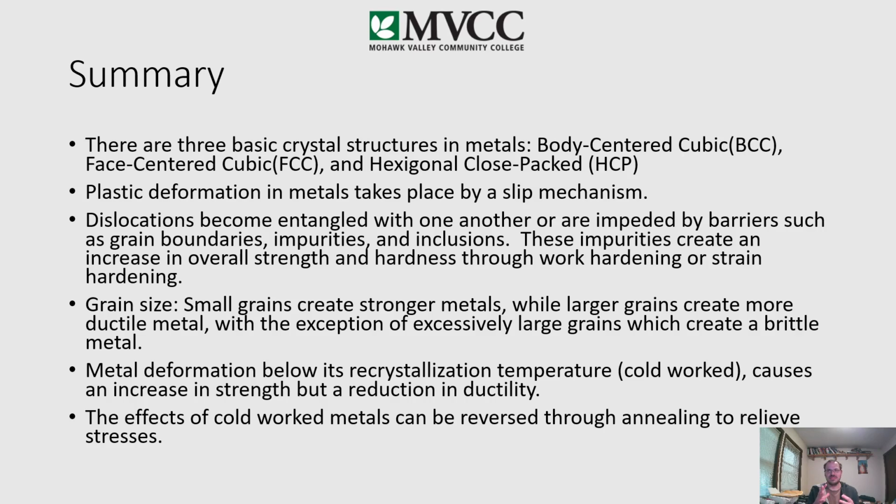They crack rather easily. But in this case, we're talking about the same type of crystals. So iron crystals versus another iron crystal, or aluminum crystal versus another aluminum crystal. The smaller the grains, the stronger it is, less ductile it is. The larger it is, more ductile, but less strength, less puncture resistance.